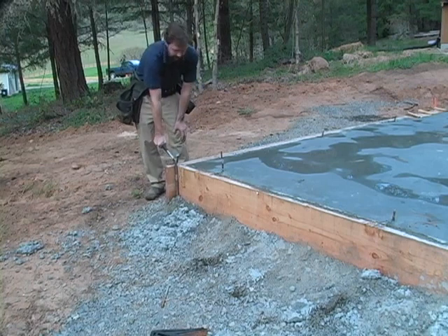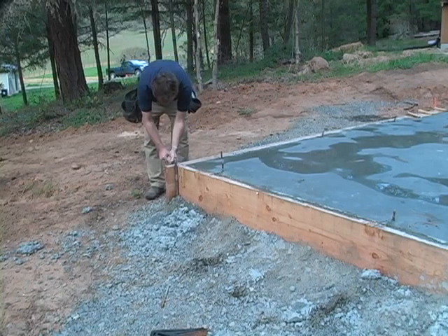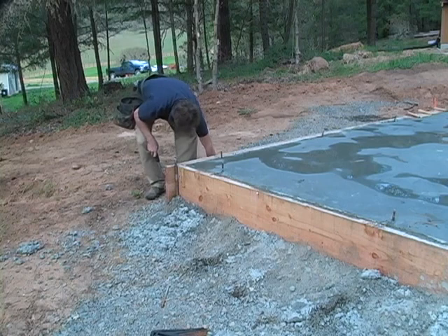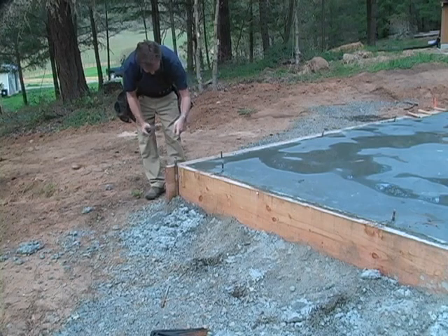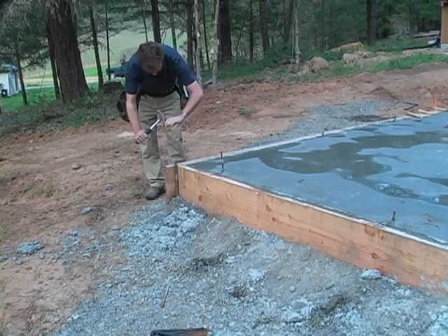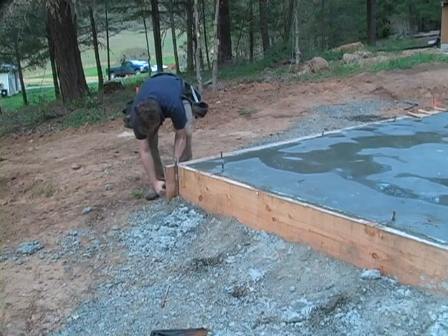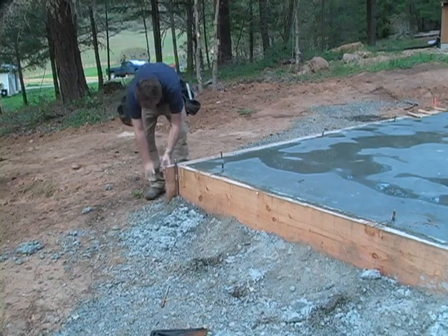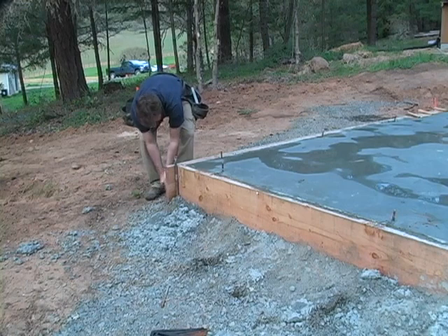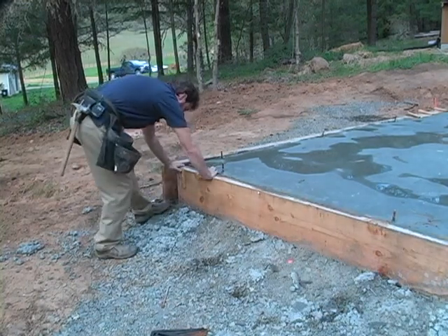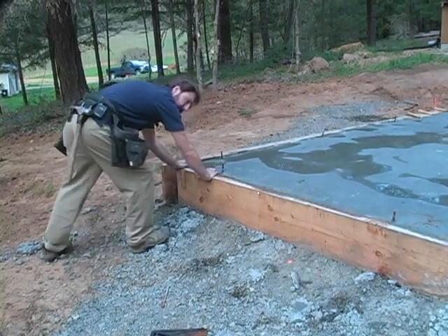And we'll pull our duplex nails. Now again, this is where the advantage of these nails comes in. Because of the two separate heads, we can drive the first one flush and then use the second one to pull it back out. So this is where it becomes a real advantage over just using a regular nail. So we've got it loosened up here in the corner, so we should be able to just kind of pop it off.